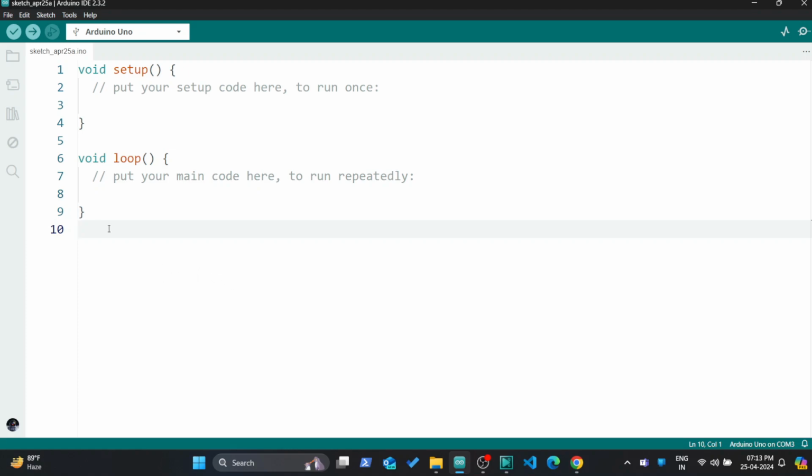Let's start off by programming the void setup function. For the Arduino to understand that we are using pin number 8, we have to explicitly program it to say that we are using this pin to turn on and off an LED. Turning on and off is an example of an output pin. This type of pin can only change the state of that pin, like turning on or off something. Another type are the input pins. They have the ability to only take data from outside to inside. Examples of using input pins are sensors. Sensors give us data instead of taking data, so we will be using input pins.